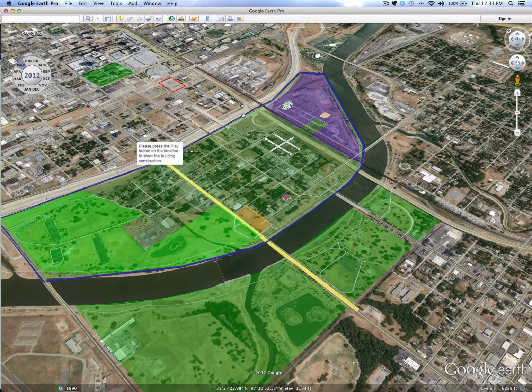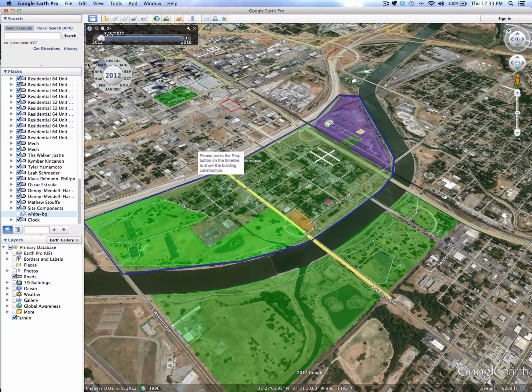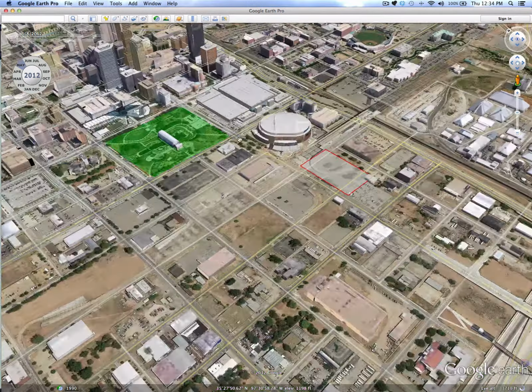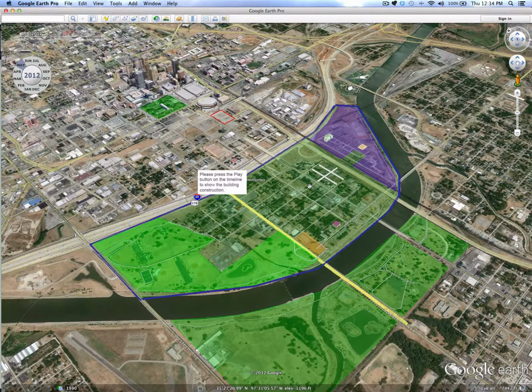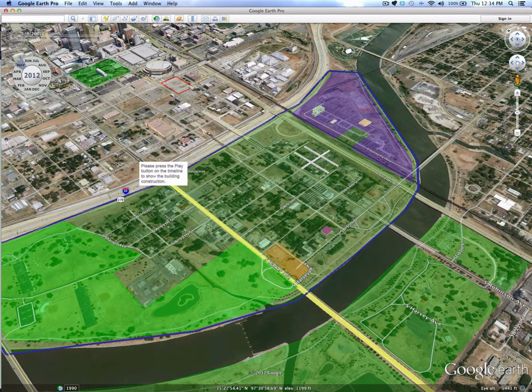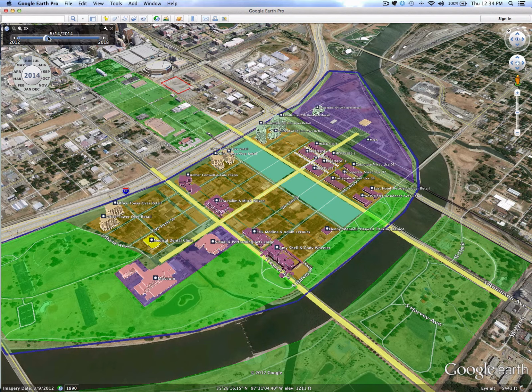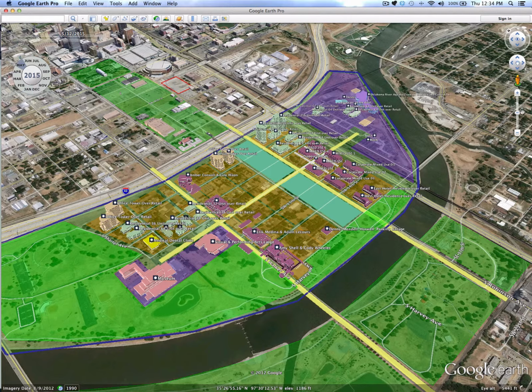So here we are in Google Earth now. In Google Earth we can also even turn on the 3D buildings that are available from Google of the downtown Oklahoma City. And we'll focus on this Quarter Shore area, the master planning area. It's a blank site because we're starting at 0 here, and we have a timeline. Each building was assigned a schedule, and each element even too, so we're showing in roads and the parcels coming in. These dates can all be easily changed, but you can start seeing the buildings coming in as we move the timeline over and hit the play button. We can actually let it just self-play here.